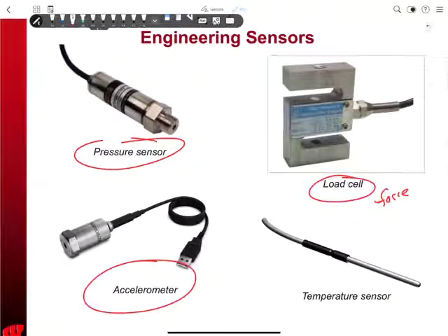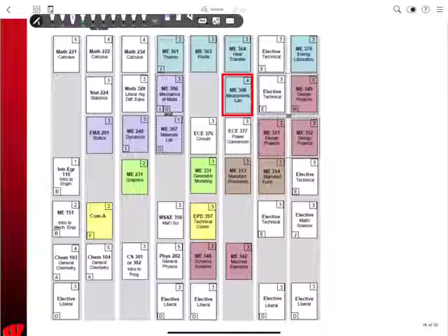that measures acceleration. Does it really measure acceleration, or is there actually a little load cell inside there that measures the force that's on something? Probably the latter. And of course, we're oftentimes interested in measuring temperature for chemical or heat transfer experiments. So these are all things that give us voltages, and somehow we have to convert that voltage to a digital signal, and then convert that digital signal to an actual force, temperature, acceleration, or pressure.